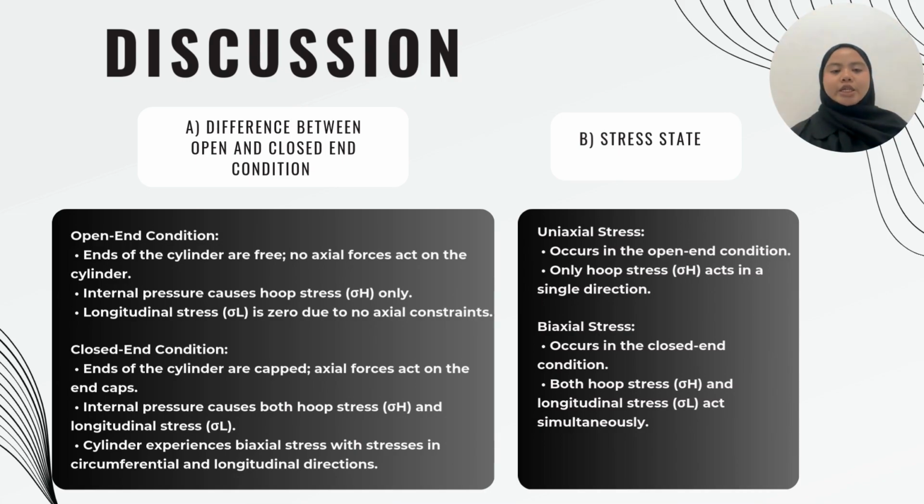So the discussion has two questions. The first is what is the difference between the open-end and the closed-end conditions. For the open-end condition, the ends of the cylinder are free, meaning no axial forces act on the cylinder. The internal pressure causes stress only in the circumferential hoop direction, resulting in hoop stress. Longitudinal stress is zero because there are no constraints or forces in the axial direction.